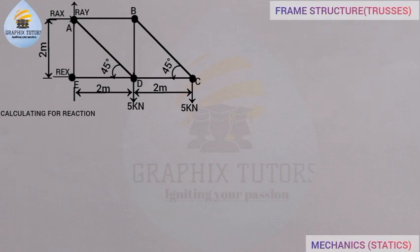So when you say summation of Fx equals to 0, it means all forces acting towards the left must be equal to all the forces acting towards the right, right? So when you say summation of Fy, or vertical component, it means all the upward force is equal to all the downward force, right? And when you talk about the moment and take summation of moment about a point equals to 0, it means that all the clockwise moment acting is equal to the anti-clockwise moment. Now we move forward. Now first take the first one, which is summation of